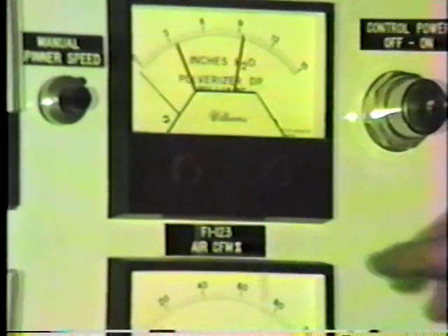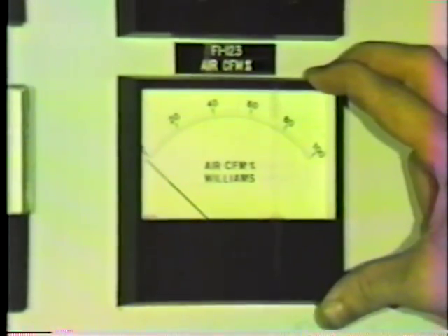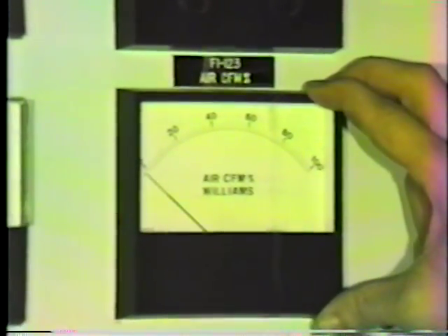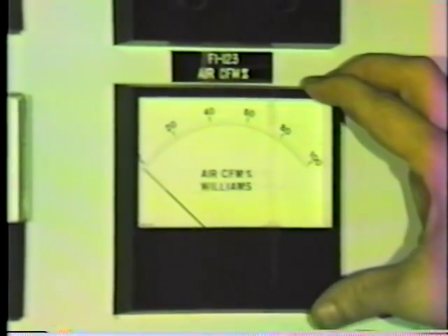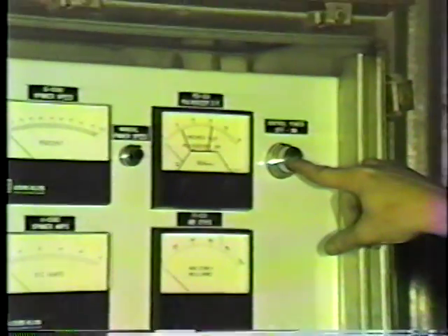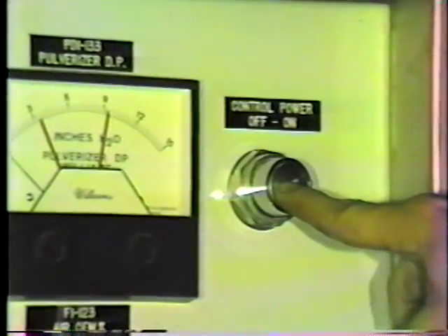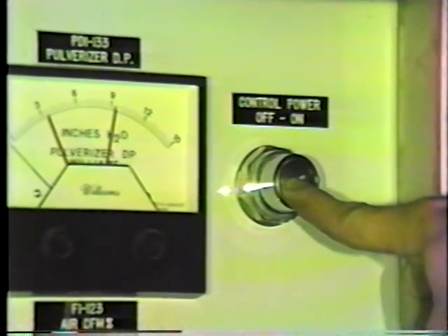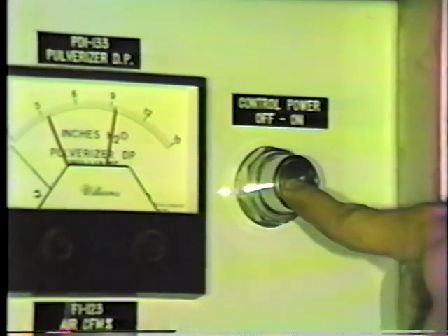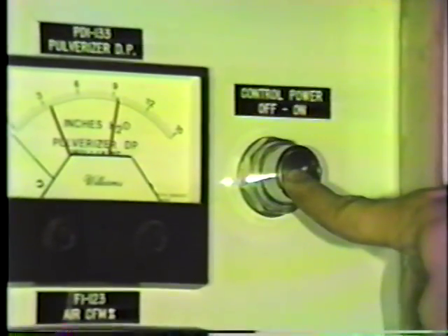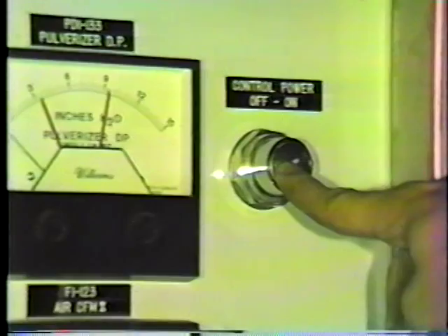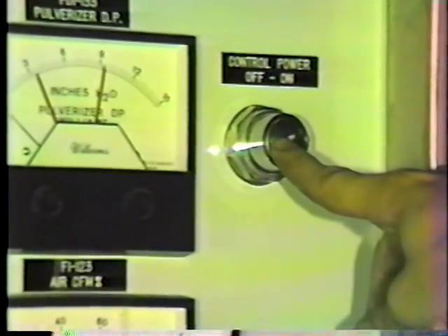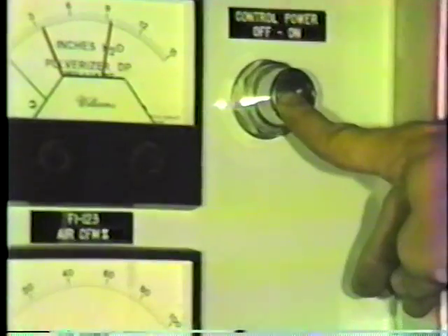All right, what's the meter below? Meter below is air CFM in the system. It's percent air that is flowing through the system. This is a Foster Wheeler feedback, and is only displayed on our board. We also have a control on-off, power on-off. There's a key switch. The only reason it should ever be turned off is if somebody is working on the system. Okay, so you've got an on-off power control for this cabinet. Right. Okay, you got anything in the cabinet you want to show us?